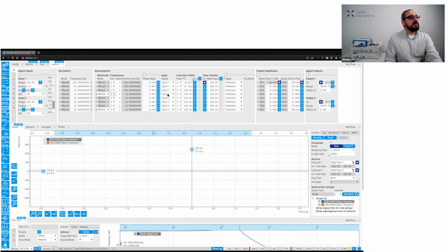Okay, so this should work. What I did so far is I am driving around 100 kilohertz on signal input 2, and I am measuring it with this demodulator, and I switched to XREF mode, and then set it up to actually control the second oscillator. And you can see that the second oscillator is now oscillating around 100K, which means it's actually locked to the...